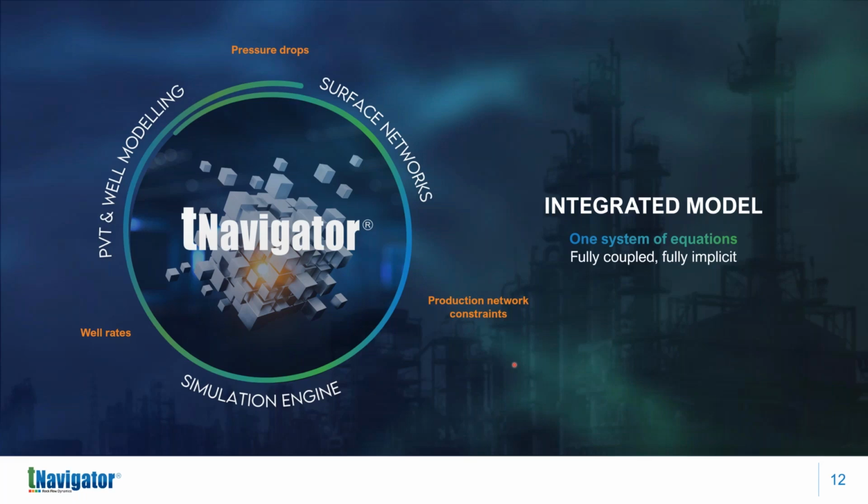Basically, we have a subsurface model with connected well models, and we can specify well rates or the amount of CO2 we can inject. We can calculate the pressure drop associated with the surface facility and check the capacity of the injection system. And we can specify the logic and specify how much CO2 we need to inject and how we distribute it between the wells.